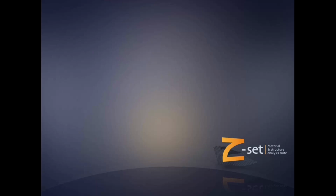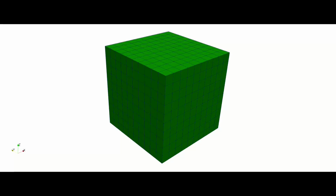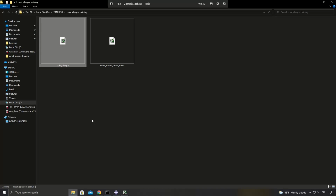For this, we are going to use a cube geometry meshed with hexahedral elements, as you can see on the screen. To illustrate the Abaqus Z-mat capabilities, we use two Abaqus simulations using the same geometry and mesh data. However, one of the Abaqus simulations, namely cube_abaqus.inp, uses the native Abaqus material definitions for elastic material, while the cube_abaqus Z-mat elastic uses the Z-mat elastic material definitions. The input files for these two are as shown on the screen.